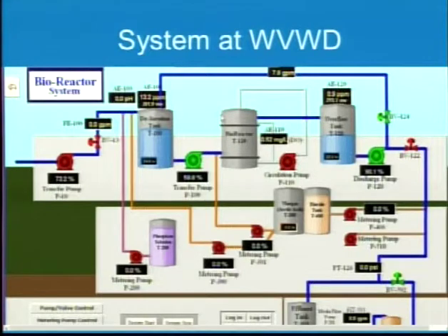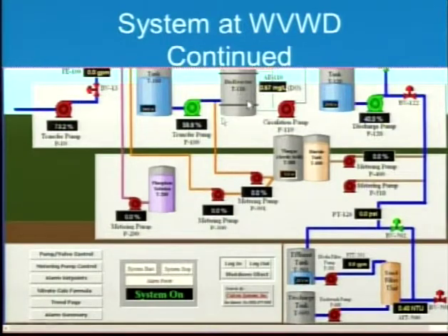We go into, well, if I can get this guy, go into a deaeration tank where we take the oxygen out, force the bacteria to eat the oxygen off the nitrate, go into the bioreactor, go into a discharge tank, and essentially at this point your denitrification system is complete. You've taken the bacteria and made them produce nitrogen gas, and you reduced all your nitrate to nitrogen gas and water.